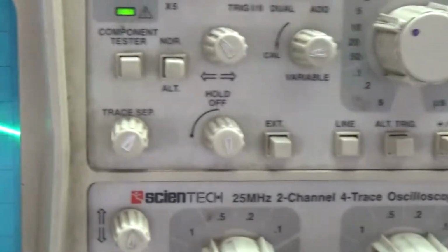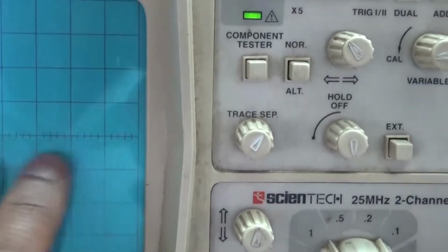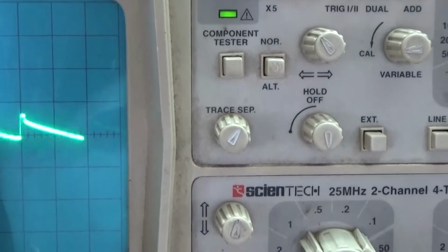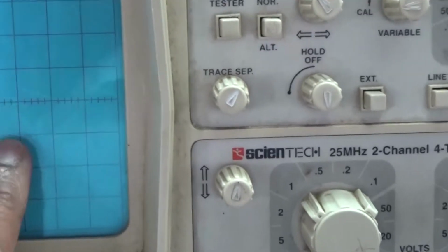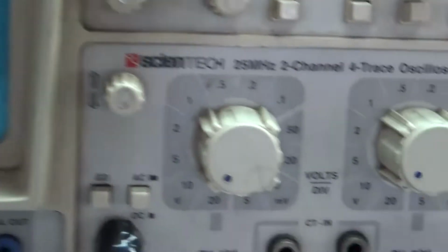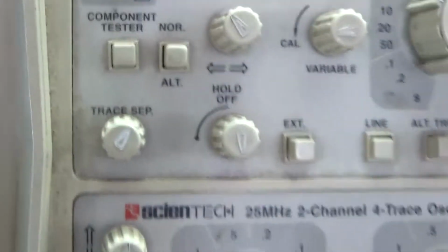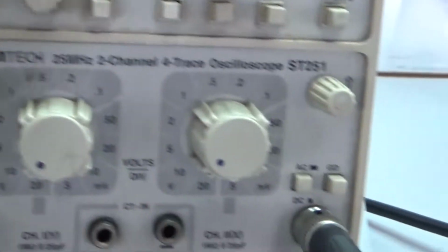Then the ramp generator. So at every zero crossing, you expect a negative ramp. The ramp starts from the highest value, that is 8 volts. It's going towards 0. It's a negative slope, so it's a negative ramp. So the amplitude of this is almost 0.7 into 10. Around 7 volts is the peak value of this particular ramp signal.